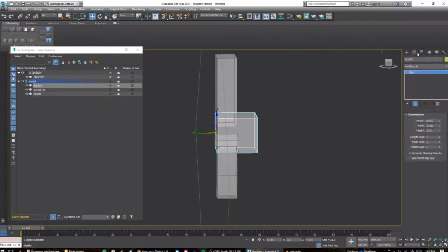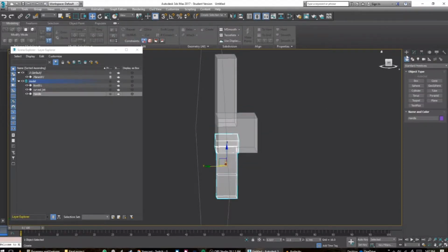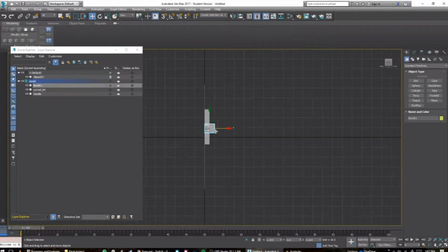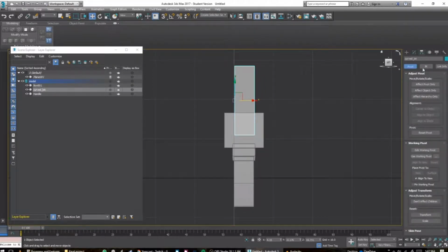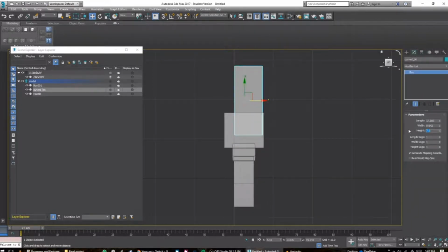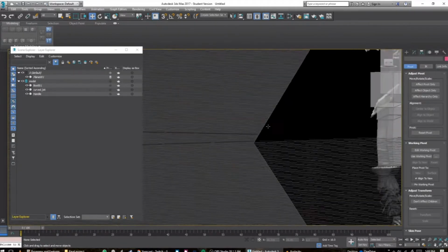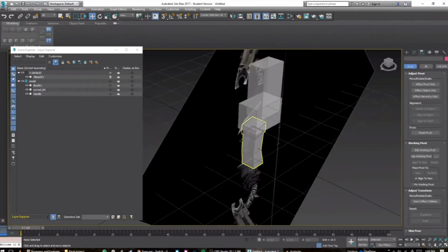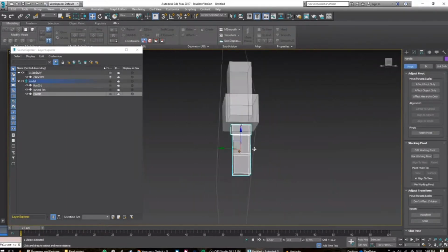Right around here, I start moving the objects into their correct height and start stacking them on top of each other in the correct ratio between the handle and the guard handle. The way I do this is I start changing their pivots to be at the center of their objects and then move everything to 0. It's a really easy and efficient way to set all these objects on top of each other while still being symmetrical.